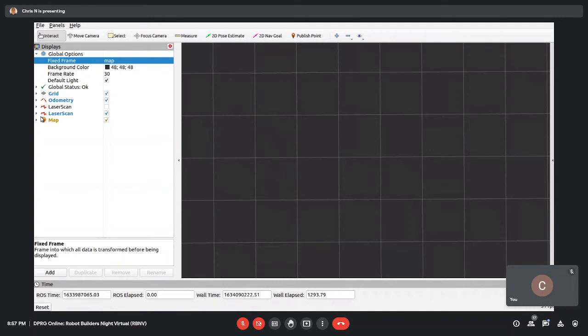It's all time-stamped, okay? So now what I can do, because some of these more advanced algorithms have 24 parameters that you can tune, and that's part of the problem, unfortunately, is you can take this recorded data, play it back, and see what the algorithm does. Like, how well does it localize? Does it get confused when the robot's turning too much? Then you can tweak some parameters and run the exact same data through the algorithm again. So it saves a lot of time and makes things very repeatable. So let me just kick this off.